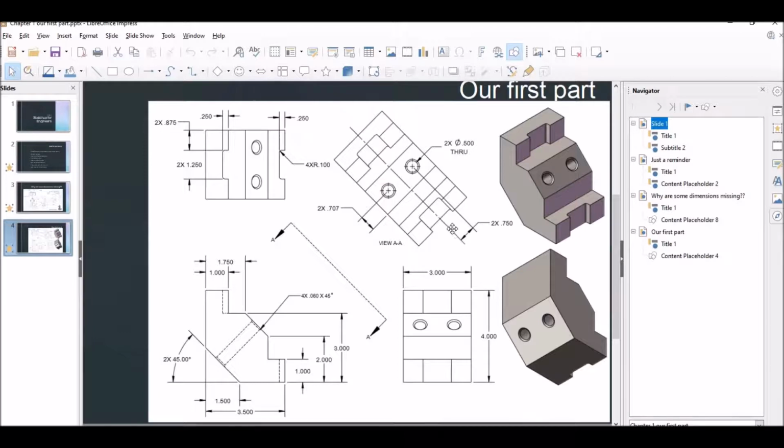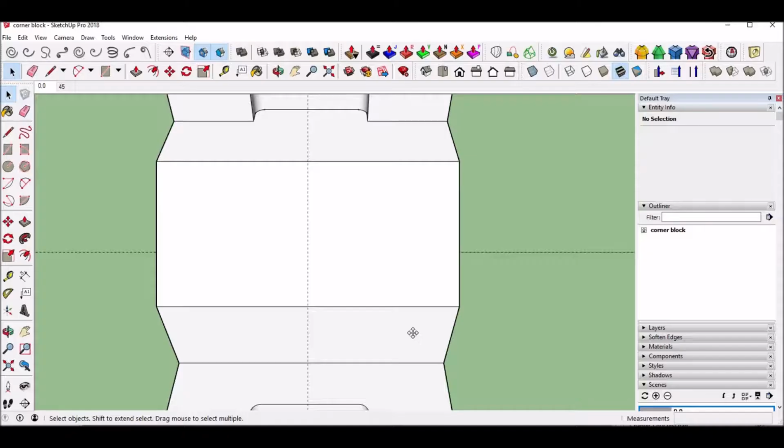So we have this center line now going along here. Let's do hole placement. 0.75 along this way and 0.707 this way. I'm going to assume that's the center, but we can't always assume that, so at least they give us the dimensions: 0.707 and 0.750, so 3/4 and 707. I'm going to hit T, and we're going to go up along this surface, 0.707. And just for kicks and giggles, it is right on center. So, alright, Control Z for that one.